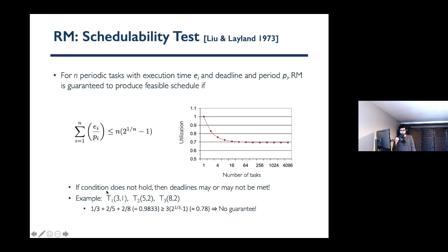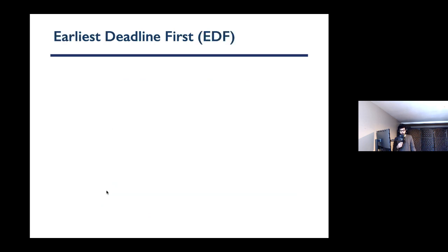Every single job in T1 had the priority of T1. So T1 had a set priority and it didn't change. We assigned priority to tasks, not to jobs, and it was not changing over time. That basically means static scheduling. Now you could do that differently, but with rate monotonic, you give higher priorities to tasks with shorter periods.